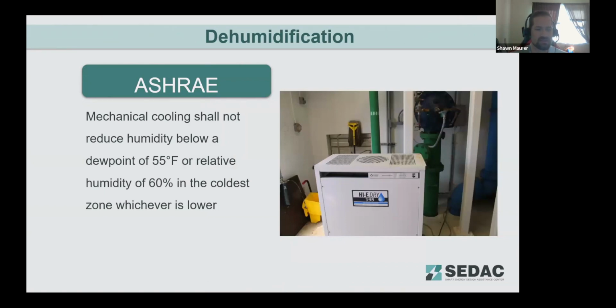Something else that ASHRAE includes that IECC does not is dehumidification requirements. For this and humidification, there are exceptions, such as specific zones in a building that require specific humidity levels, such as museums, hospitals, certain areas that have really tight tolerances for the purposes of running tests or optimizing the healthcare environment. But those areas do have to be specifically approved by the authority having jurisdiction to be exempted from the dehumidification requirements.